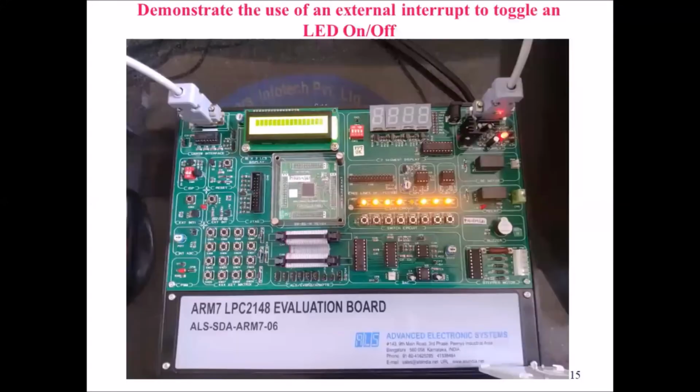Here you can see the LPC2148 microcontroller board. This is external interrupt one, EXTINT1, EINT1, and there is a push down button. When you push this button, the light will turn on. When you push the button again, the light will turn off. That's how the external interrupt works.